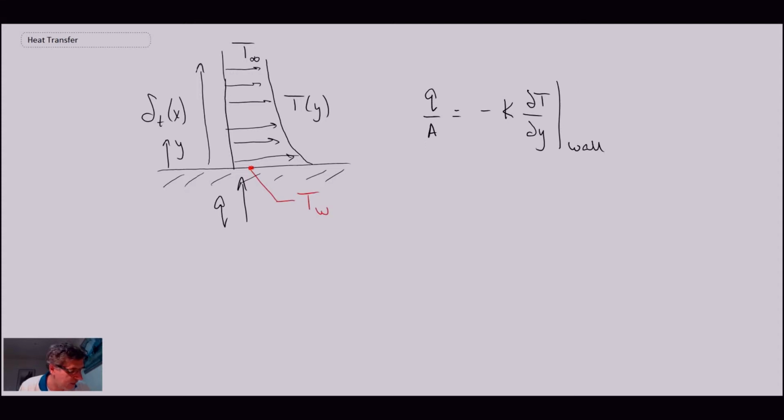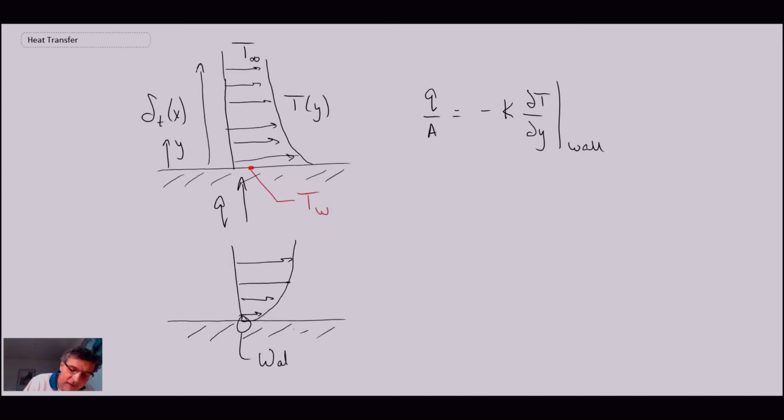And what that means is right along the wall, if we look at the velocity profile, that's not a very good plate. Let me do this. Okay, so here is our flat plate. And if we look at the velocity profile right along the wall, if you were to go microscopically into the wall, at the wall, the velocity is 0. U at y equals 0 is equal to 0. And so that is what we call the no-slip boundary condition.